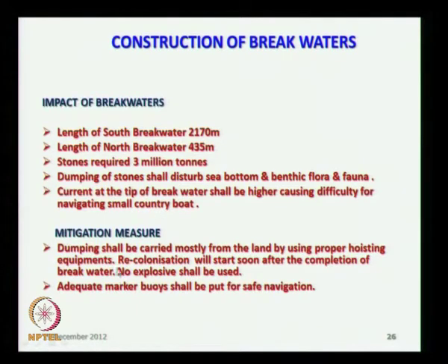The mitigation is that dumping shall be carried out mostly from the land by using proper hoisting equipment. Then the recolonization of the benthic flora and fauna will take place immediately, and we should not use any explosives or anything like that at this location, mainly if you want to make a trench. And you have to make marker buoys for safe navigation from the tip of the breakwater. You should mark some distance so that they know where the tip of the breakwater exists.